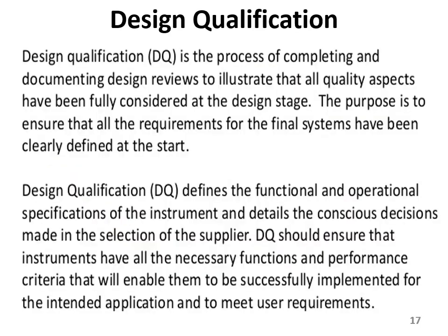Design qualification. Design qualification, DQ, is the process of completing and documenting design reviews to illustrate that all quality aspects have been fully considered at the design stage. While you are designing the process, you have considered all the possible things which you are going to see or face during the process. The purpose is to ensure that all the requirements for the final system have been clearly defined at the start. At the start, you must define each and everything.